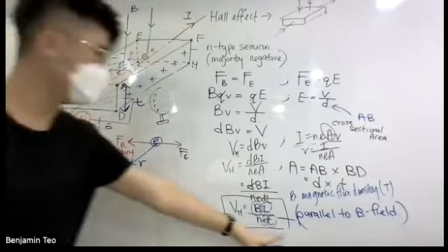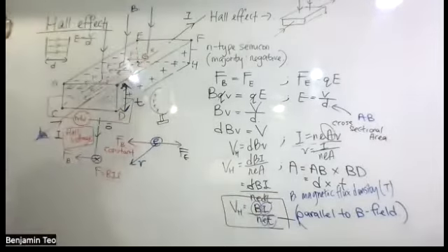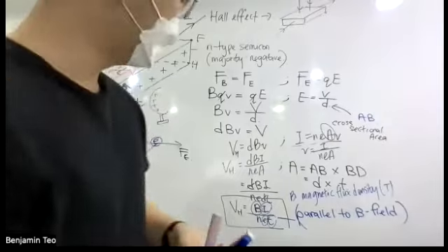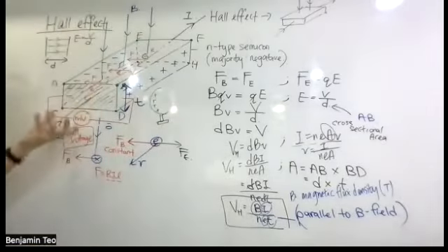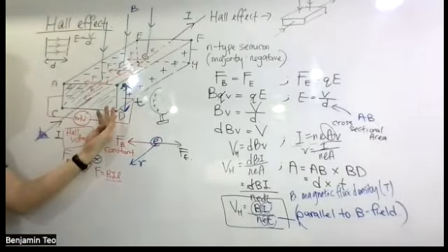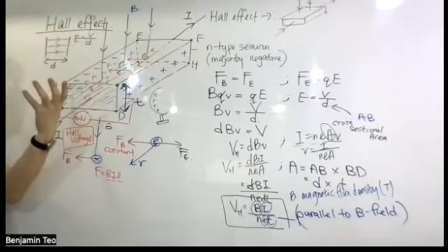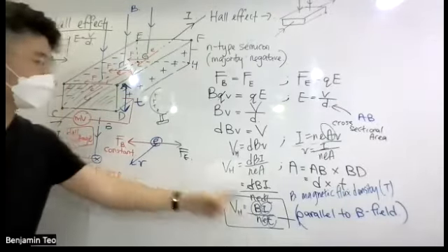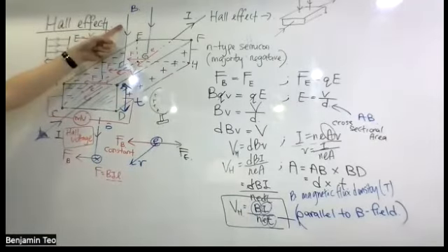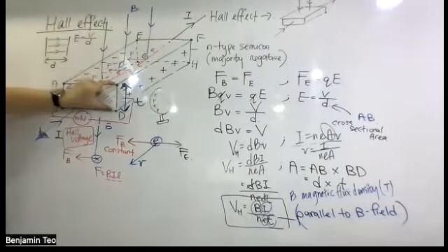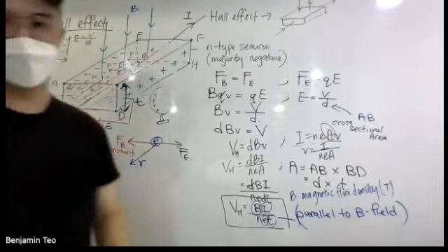Faster, you can identify, because I can give you a square. This one is a rectangle, but sometimes they give you a square, so where is the thickness? Or if I rotate this magnetic field, or even change the current I, where is the thickness? You see the magnetic field. Parallel to the magnetic field, this side is the thickness.